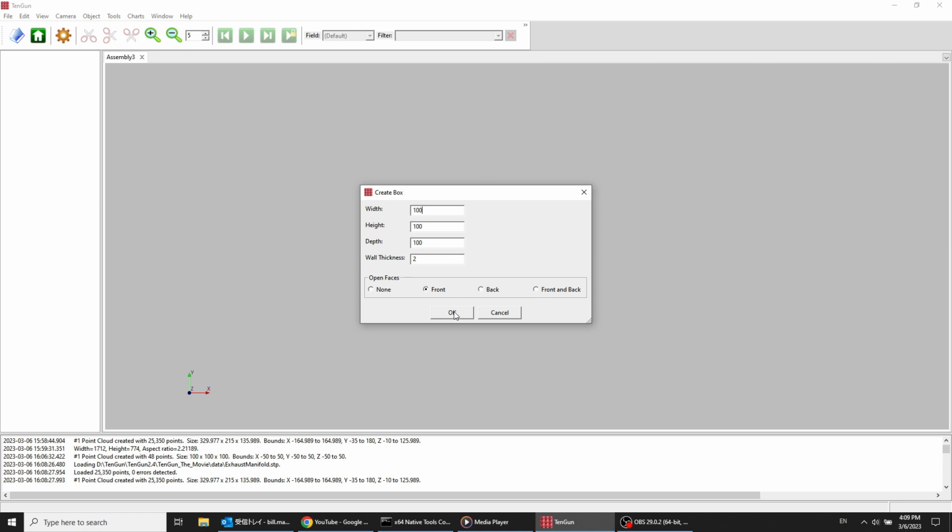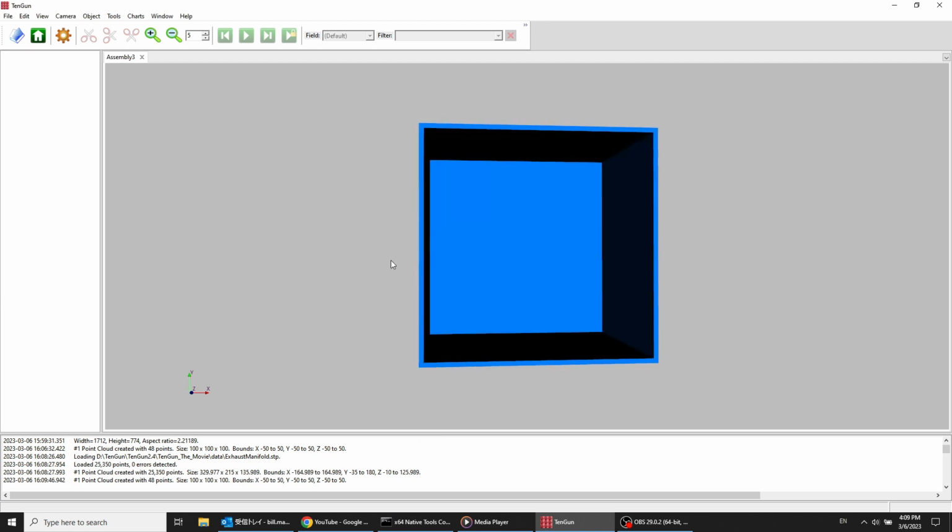Notice that the default dimensions of each object are 100 units, and for an SPH application the units will typically be millimeters. Also note that objects are centered, so you will probably need to move something later if you are working with multiple objects.